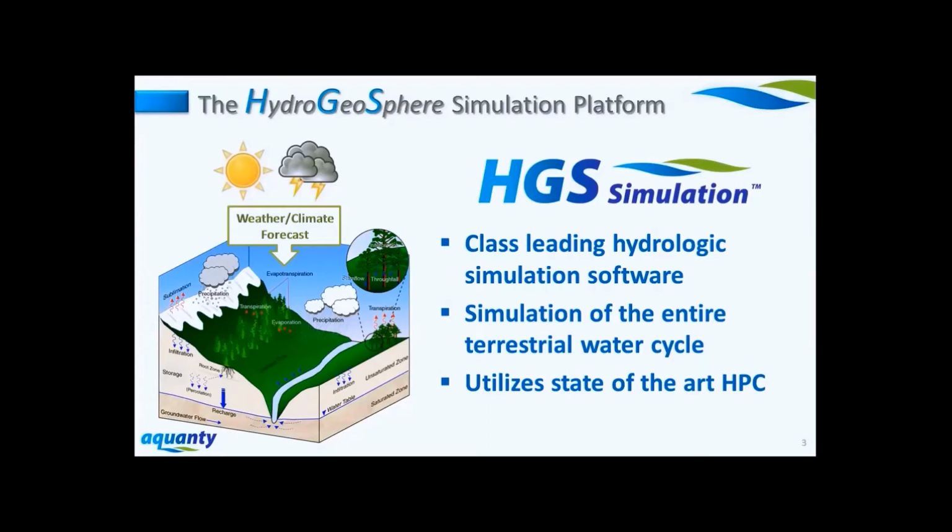using a physics-based approach. So HydroGeoSphere is based on partial differential equations over the entire land surface. For water flow, we solve the 2D form of the diffusion wave equation. And in the subsurface, we solve the three-dimensional form of Richards' equation. So it is somewhat unique in the sense that we take a globally implicit approach and we solve these differential equations simultaneously at each time step.